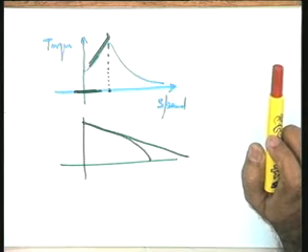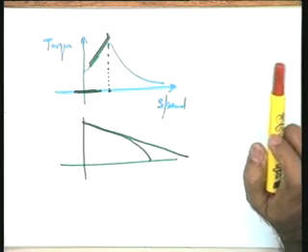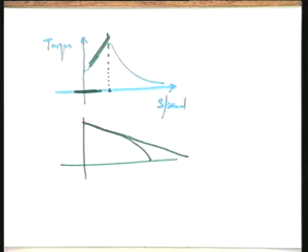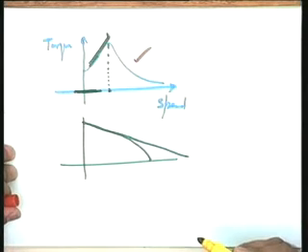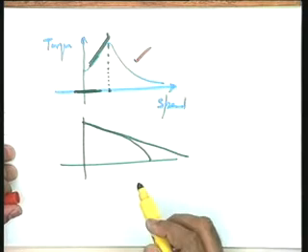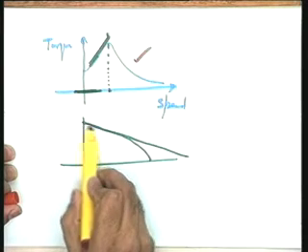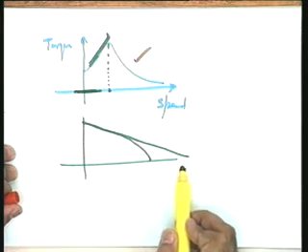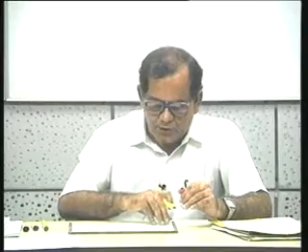So you are paying a heavy price as far as efficiency is concerned. High rotor resistance means the net efficiency of the motor is going to be low, but naturally we cannot help it, because our specific application is a servo application wherein the negative slope is not allowed. So this point has to be kept in mind: if you are using an induction motor for servo application, redesign it or take care that it always has a positive slope. Okay. So with this now I can go back to the motor model.